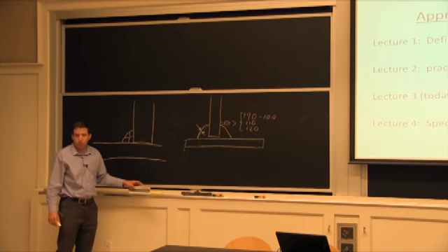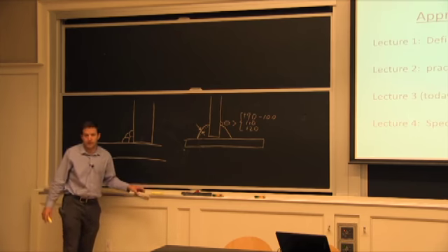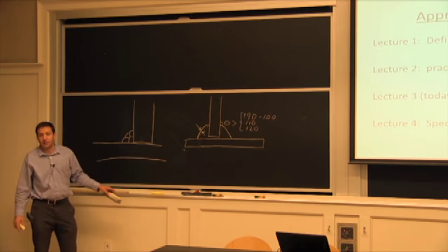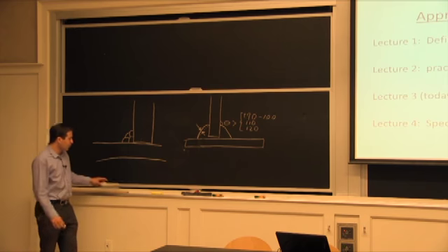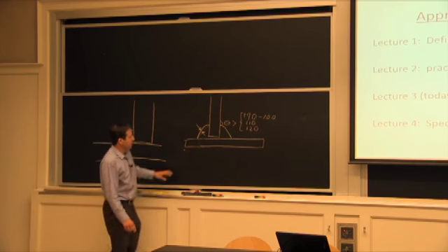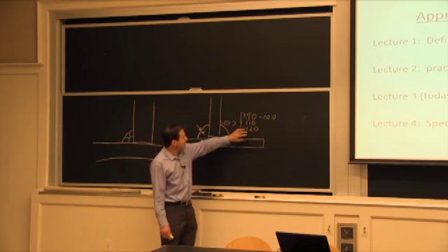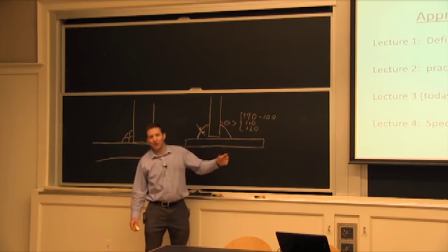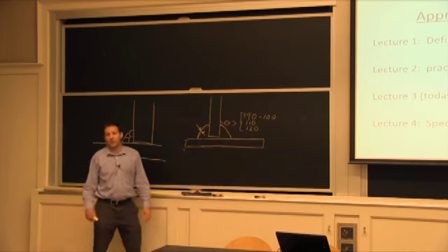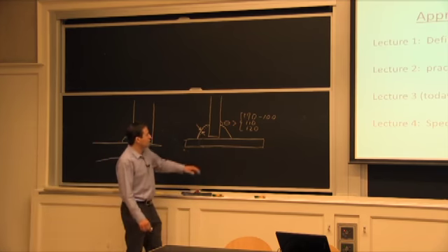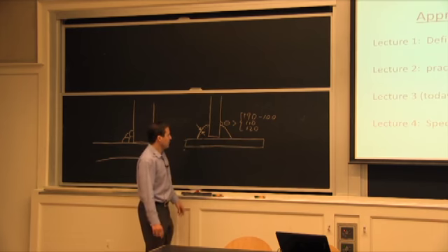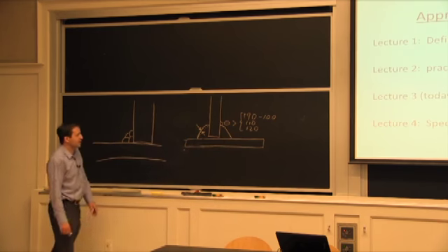And it's the case, and people will do it. They'll say, hey, no, this is not a good weld. It's not acceptable because I believe you don't have the fusion. But it's a more qualitative description than saying, well, you're on the edge, you got 110 degrees, or you got 100 degrees, or whatever the number is from your estimate. So this allows to quantify, and that's another topic that Professor Eggers taught us in this class.